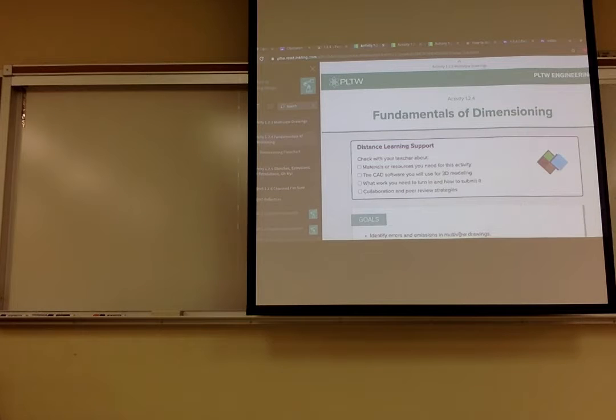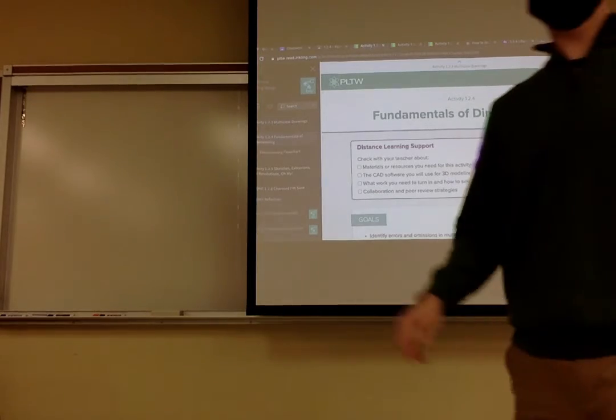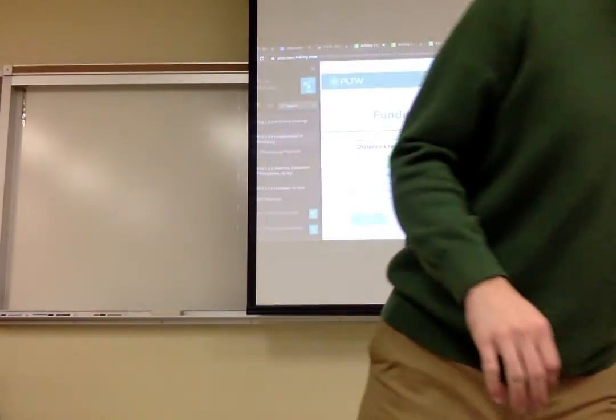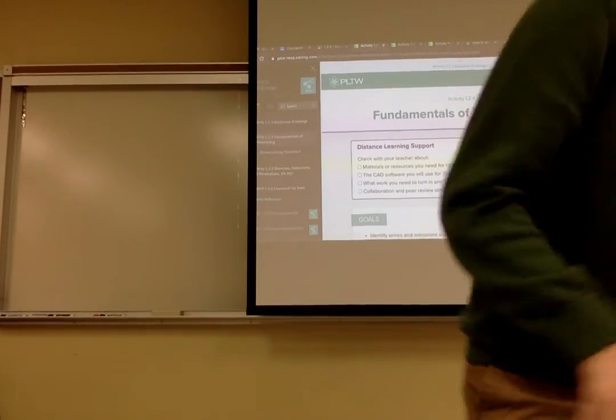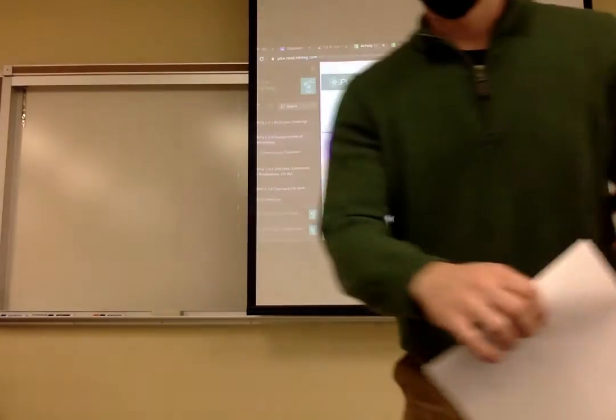So you want to dimension from center to the edge of an object, so that if I were drilling a hole, I'd go to my edge, measure, and drill here and here, right? So you could basically just go center to this edge, tell me what that is, center to that edge. How do you want us to figure out the diameter of it? Well, that one you dimension here.